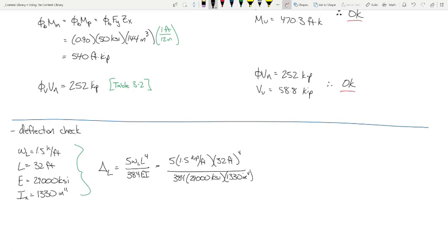Units. Y'all remember when we computed deflections in structural analysis, we had a magic number that we used? 1728. It's a magic number that converts cubic inches to cubic feet. It's like that stuff we did last semester has value. It's crazy. So what are we getting here? 0.918. 0.918 inches.